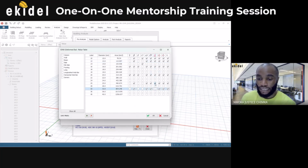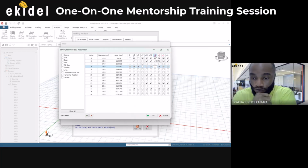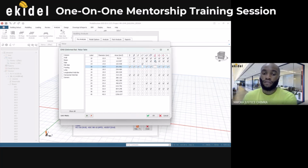So I will check this one that are big. For links, oh, okay, stirrups. Yeah, stirrups. Half inch and 3/8, so it would be the 12 and the 10 and the 12.7. Okay, so let me just say 10 and 12. I'll choose 10 and also 12 here. That's fine. Then I'll just uncheck the rest.